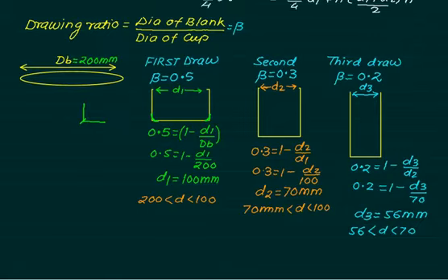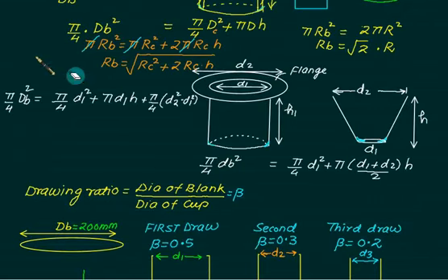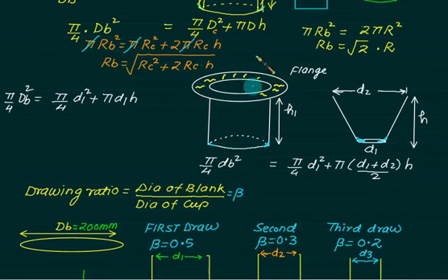Second thing, a flange like this. Suppose we are getting a flange in this fashion. Now when the flange is prepared, this part is stuck with the die and this part gets compressed. Because of this, there is a cracking problem. This is a very common problem in a flange. So actually this part is held in, this part is the holder. So if this holder plate pressure is less, then the wrinkling problem is always there. Secondly, if there is solid material here, it will try to expand and push in this fashion. So this is how you get a wrinkle.